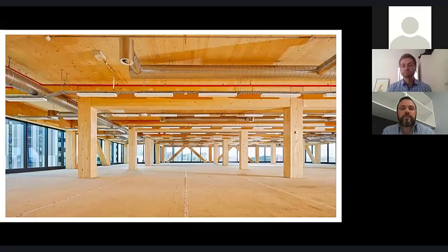And it leads on to this point. So this is a commercial office. It's one of Lend-Lease's jobs. They've built quite a few. They look fantastic, really innovative, a lot of exposed timber. But the whole discussion we wanted to send out really today is to start looking at a potential solution that is a post and prop commons, to incorporate that into these types of buildings like a hotel, which allows the loading to be completely free on the active deck or the decks below with no propping.